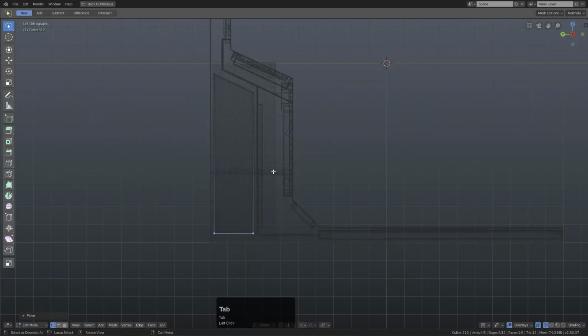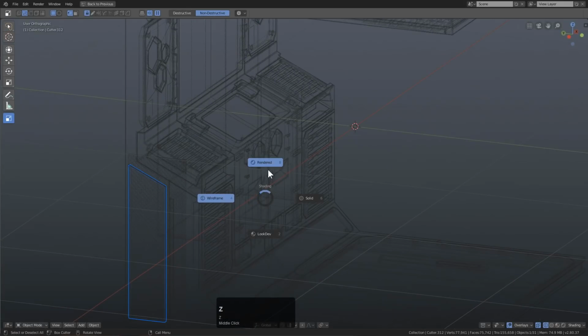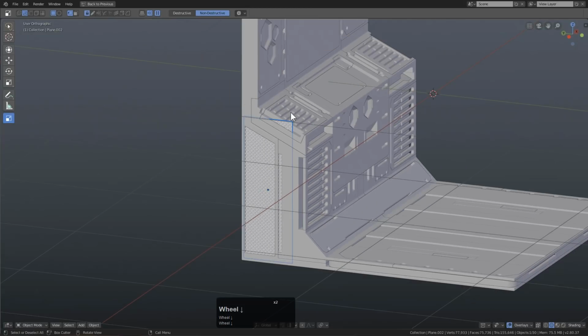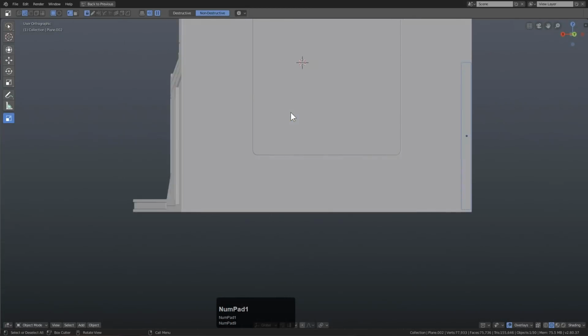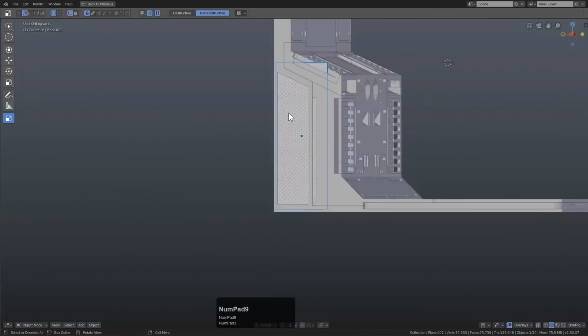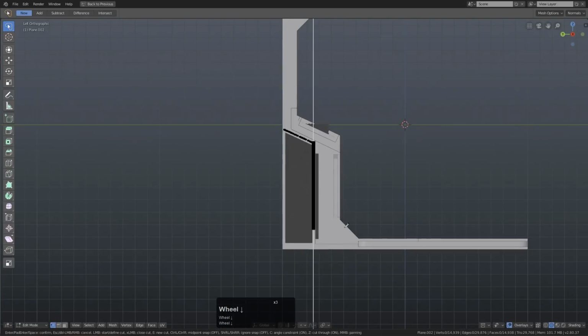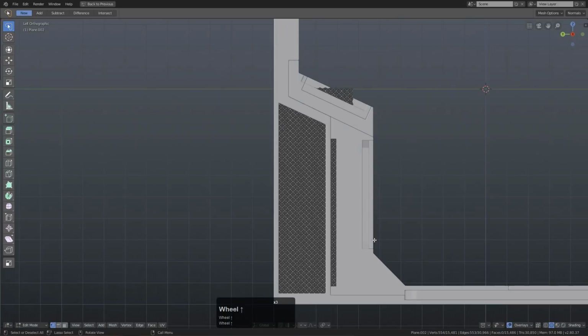Z is a button y'all just shouldn't mess around with, but making it turn into this pie menu just takes a little getting used to. Really, that's all Blender is, right? Take a moment to stop complaining and just try it long enough. It'll make sense. So right here, I'm using a knife. I'm going to press K or Z for cut through, and then I'm going to press C for constraint, and we're just going to cut an edge here. Press V, Control L. Sheesh.